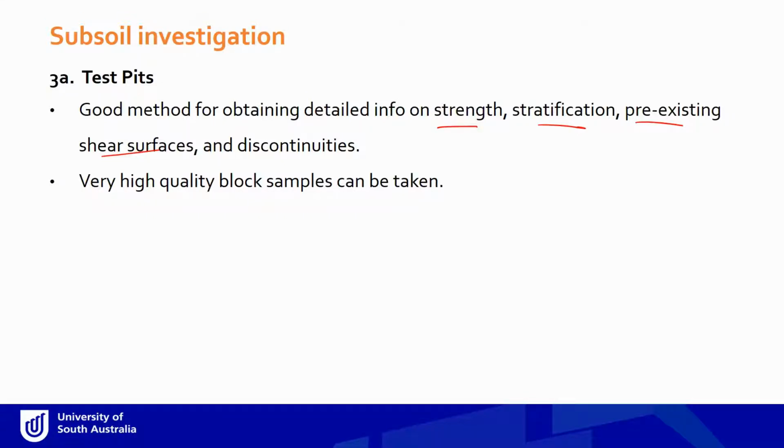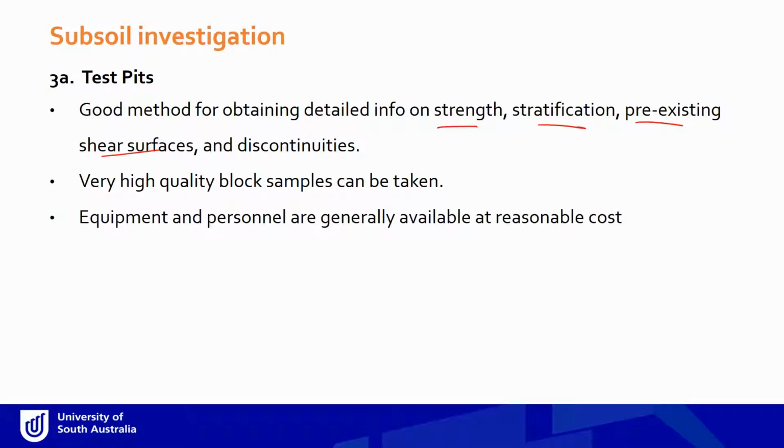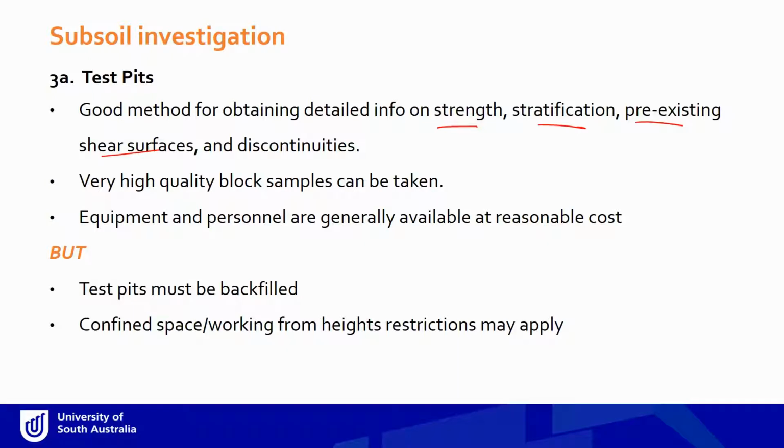So high quality block samples can be taken, and equipment and personnel are needed. They're with reasonable cost, and we don't need very experienced or skilled personnel to dig a hole into the ground as well. So that's a good thing. Now, on the flip side, test pits, obviously, if you dig a hole before construction, that needs to be backfilled. Also, sometimes confined space or working from height restriction may apply.